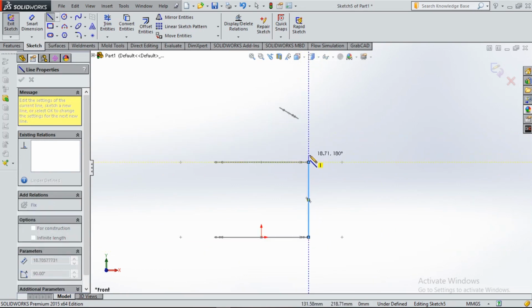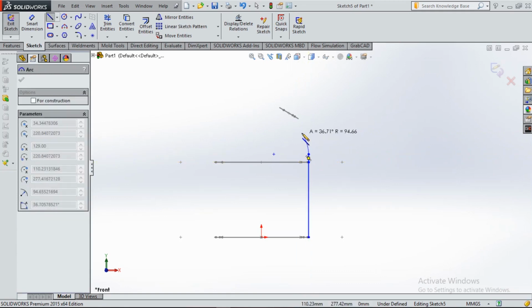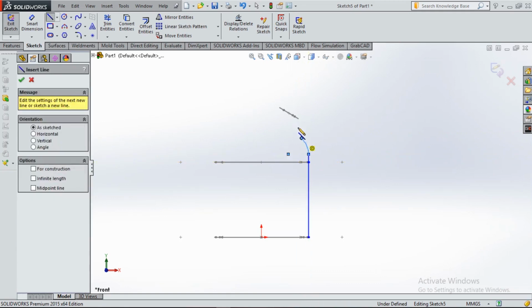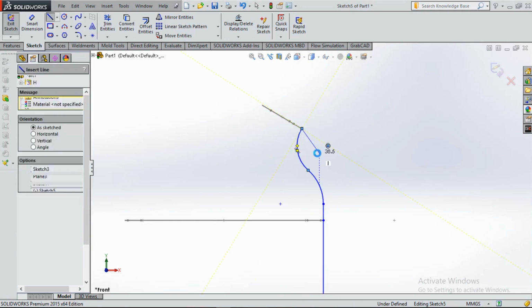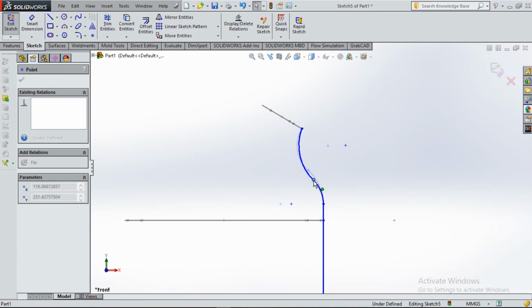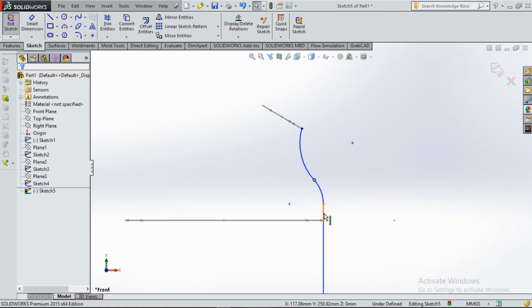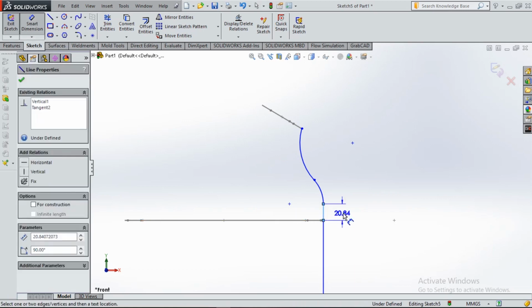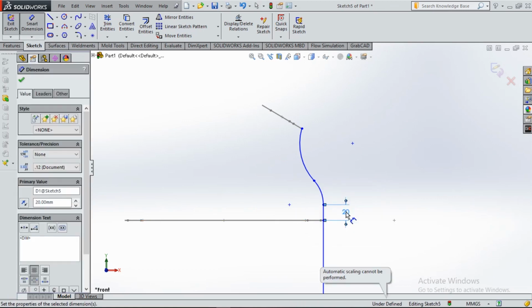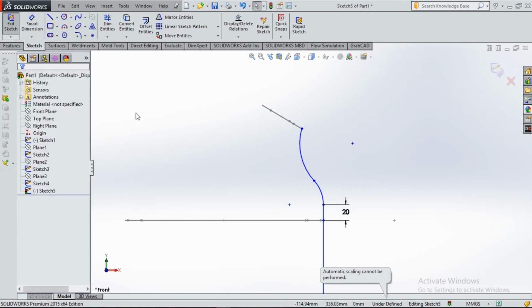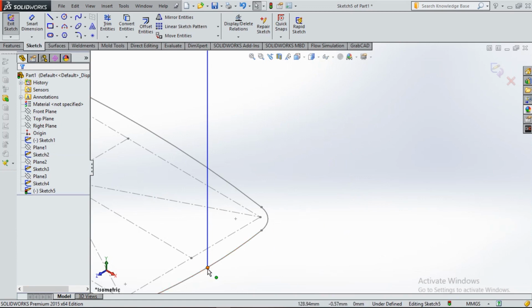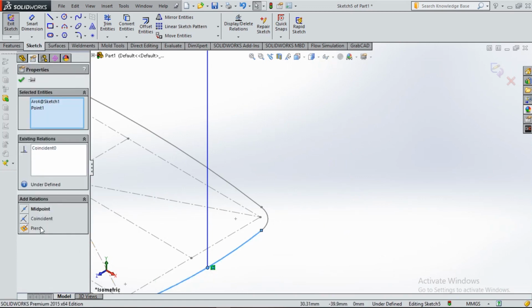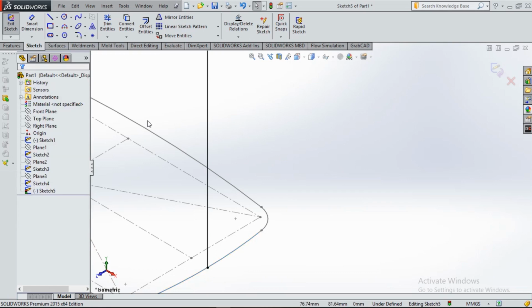Okay, so I'm going to be sketching on the front plane now, and I'm going to link my sketches together from the top to the bottom. Of course, this was the same process we followed when we were going through the loft command, how we used these open loops as guide curves. But for the boundary boss base, it is called an open loop. These are open loop sketches.